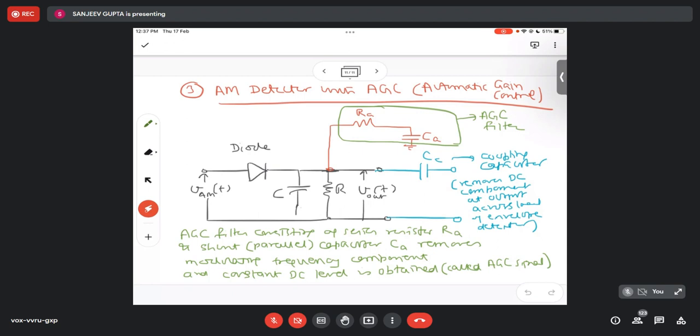Sometimes if somebody is giving a broadcast, suddenly the volume goes high and suddenly the volume goes low. So there must be some automatic gain control also at my detection stage, at my receiver stage, which is in my radio, not in the transmitting station, the Doordarshan station. So I should have something for that also, so that my volume remains constant. So there we add an AGC filter.